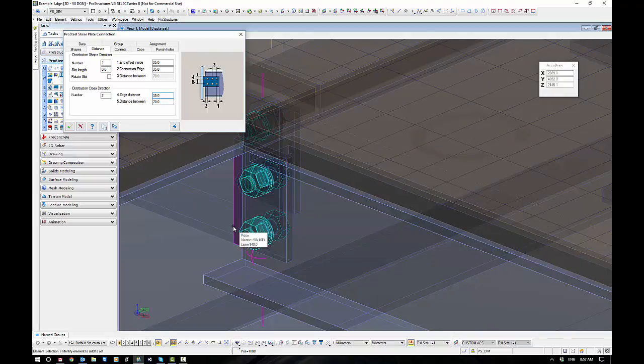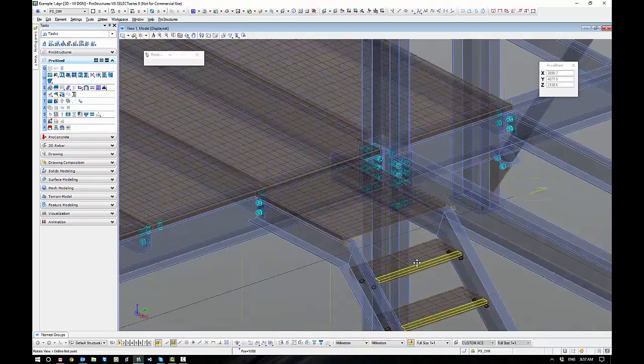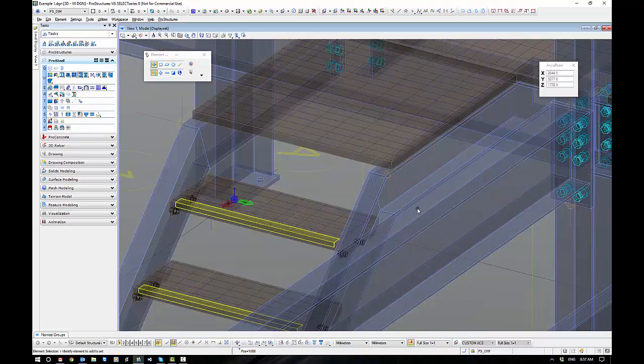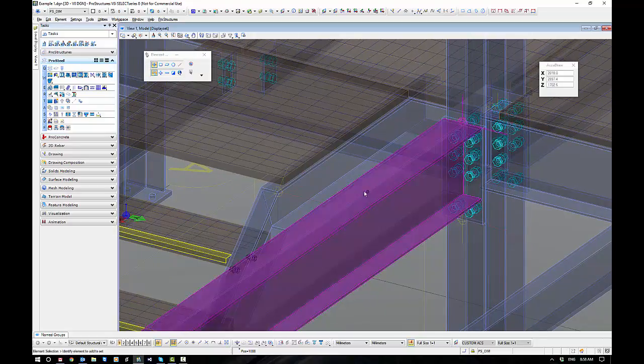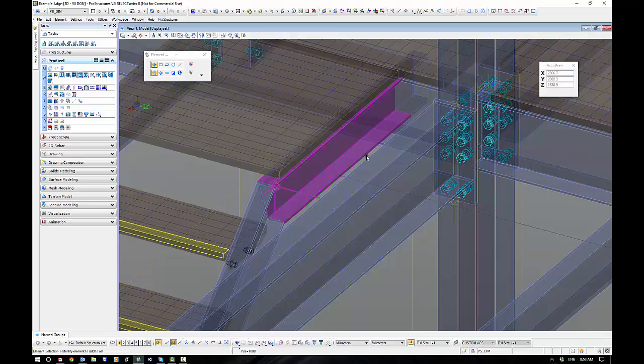There we go. And nice and neat, you'll see it's coped in there, and don't forget to check what side this cleat is on. Can we get this connection together, which is really important for automatic connections. Alright, let's have a look at this other side. Now, there's a little bit of a tip to this, so let me just get my view sorted out here for you. If we have a look at the element coordinate system, ECS, you can see here the blue line points up on that PFC. This one here, look, it points down, which means the top of steel for that member is actually on the underside. It is a bit of an issue with the way it was coded, because this function is very, very old, which means we've got to be really careful when we put this connection in, supported to supporting.